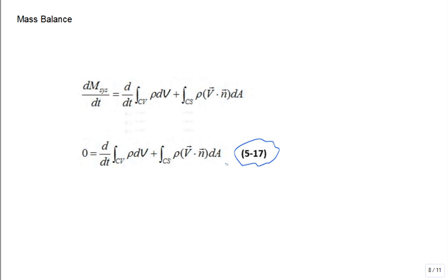Do we have any mechanism by which the mass of a system, a closed system, is destroyed or generated? No. And so basically, that has to be 0 because mass isn't destroyed or generated. But on a focused region of space, you can have an accumulation of mass because maybe the density increases with time, or goes down with time.